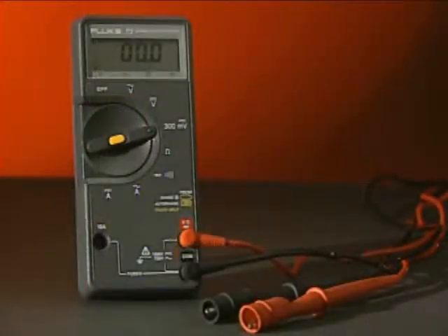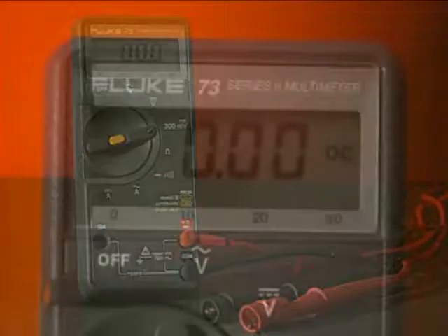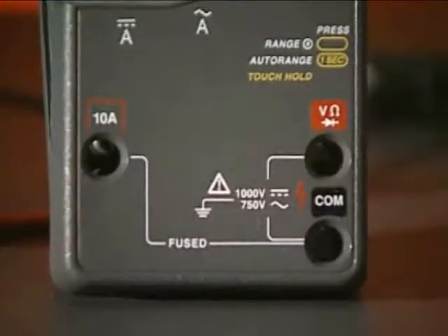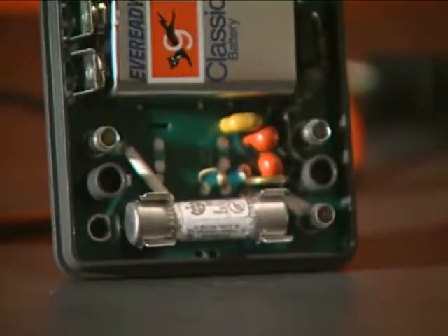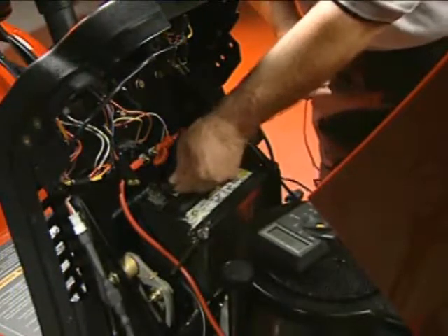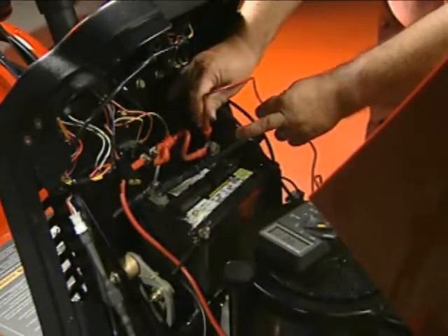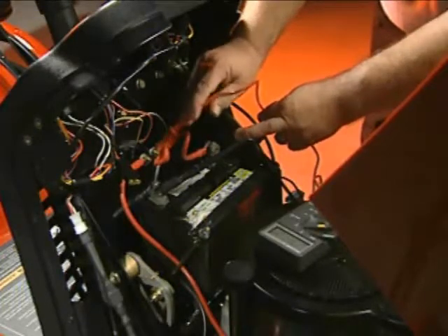This digital multimeter is equipped with a fuse to prevent damage to the meter in case the input limits are exceeded by mistake. If the meter displays a reading of 0.00 when testing DC output, check the fuse in the meter according to the operating manual. Your digital multimeter is a valuable tool. Knowing how to use it will help you quickly pinpoint the source of electrical problems.